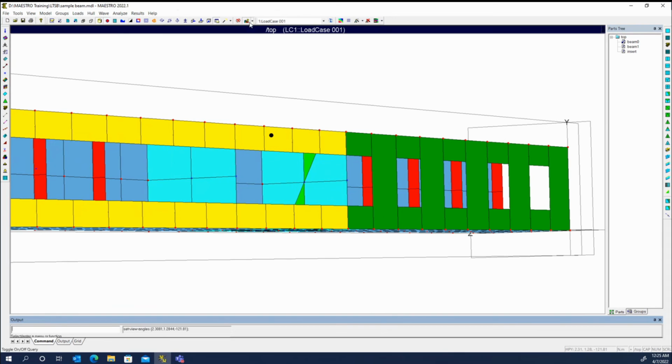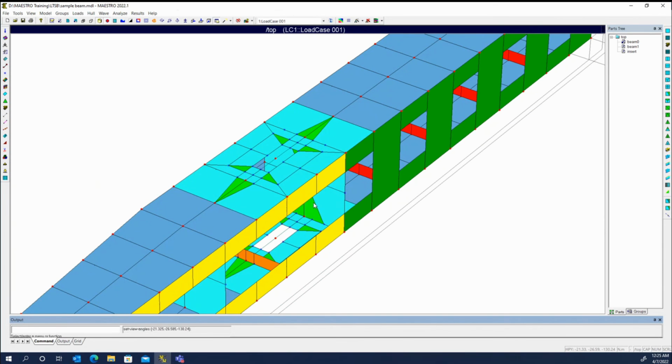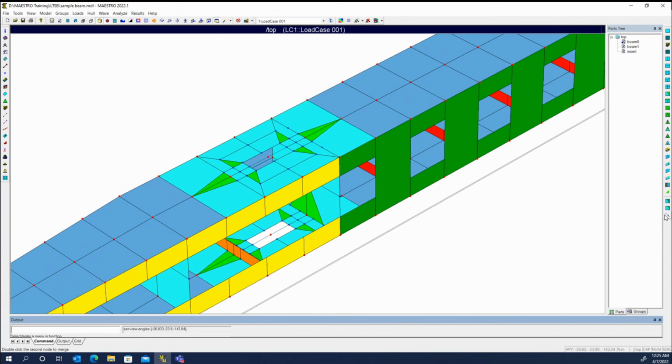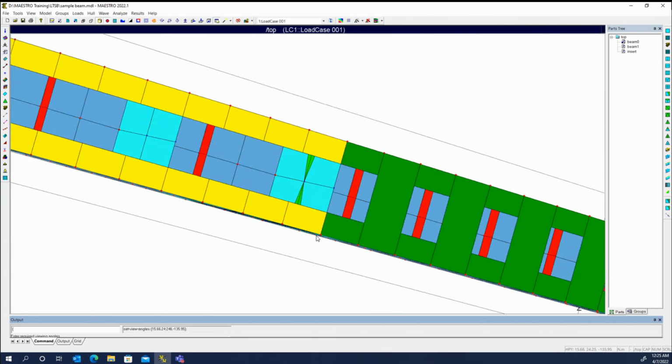I'll use the dynamic query. Let me turn off the nodes there to flip the pressure side on these 2. Then I'll go back to the split, quad, and try. And now I have the nodes that I want just in the wrong spots. So we'll use the merge additional node. And that should have cleaned up all of our edges.